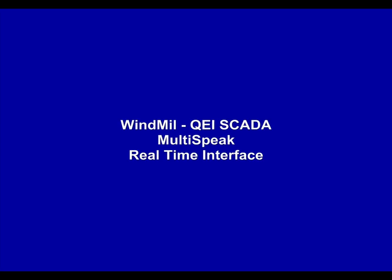Now that we've demonstrated the AMR interface, we'll show Windmill interfacing with QEI's Scada system. Throwing a Scada system into this mix allows us to take another step down the path towards accurate load modeling. Because a Scada system can supply up to the second readings of phase currents at the feeder breakers, we can run Windmill's load allocation analysis at any time of the day using the actual phase currents that are being measured at the feeder at that instant.